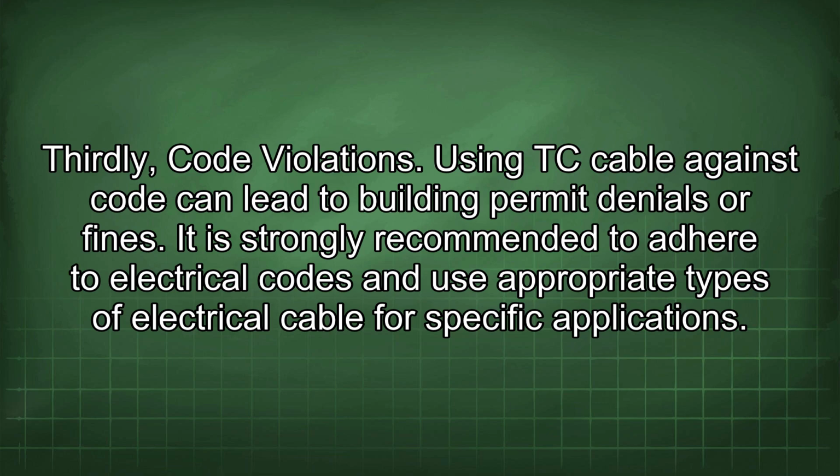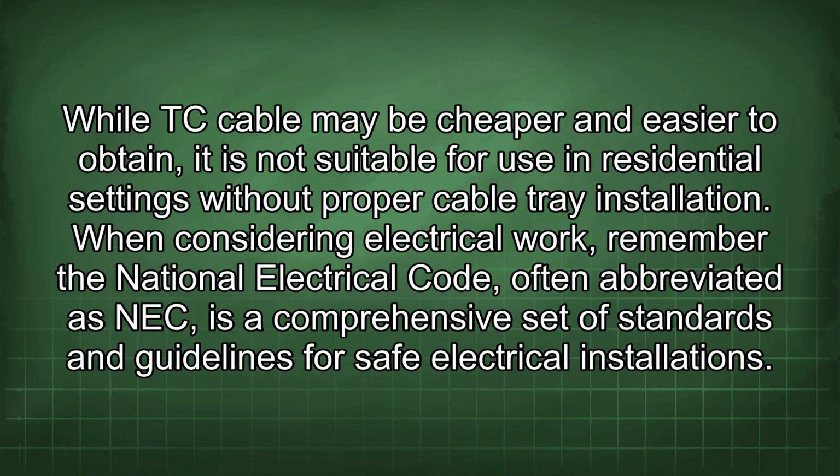It is strongly recommended to adhere to electrical codes and use appropriate types of electrical cable for specific applications. While TC cable may be cheaper and easier to obtain, it is not suitable for use in residential settings without proper cable tray installation. When considering electrical work, remember the National Electrical Code, often abbreviated as NEC, is a comprehensive set of standards and guidelines for safe electrical installations.